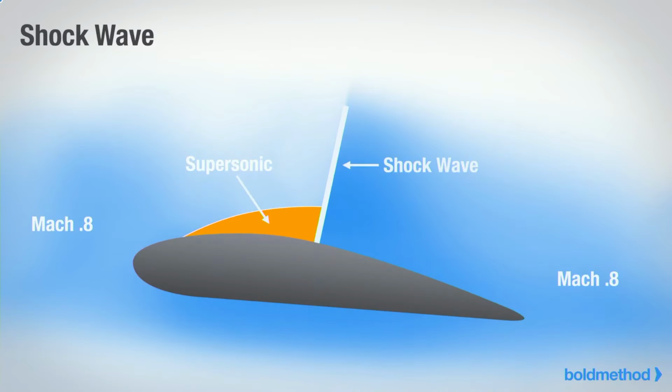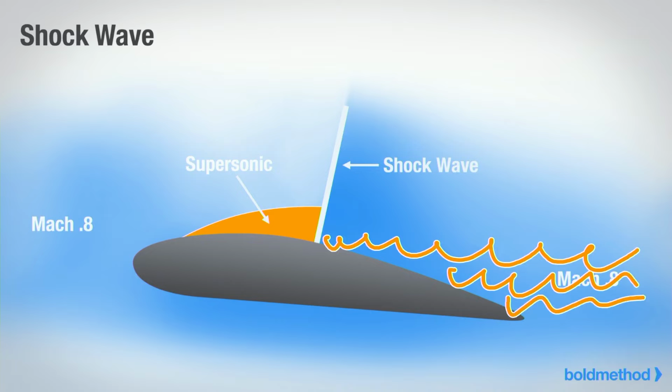Okay, let's go back and talk a little bit about what's happening with this shockwave again. We've talked about the fact that once you generate the shockwave, even though the airplane is not going supersonic, as soon as that shockwave shows up, we can start to run into problems because we can generate separation. We also talked about the fact that as soon as the shockwave shows up, lift that at one point in time might be centered here can start to move backwards possibly on the wing.